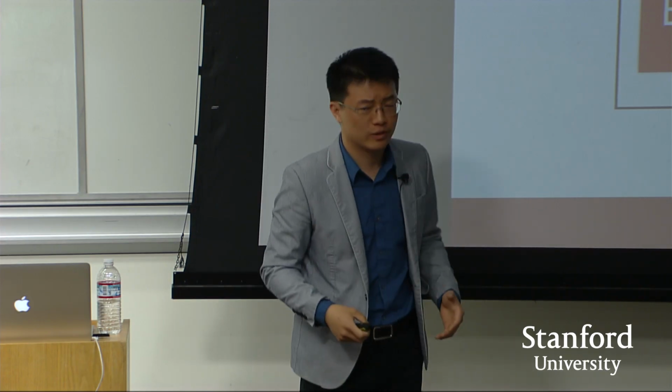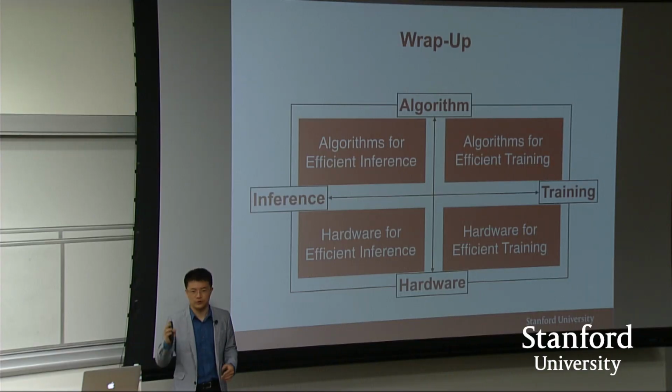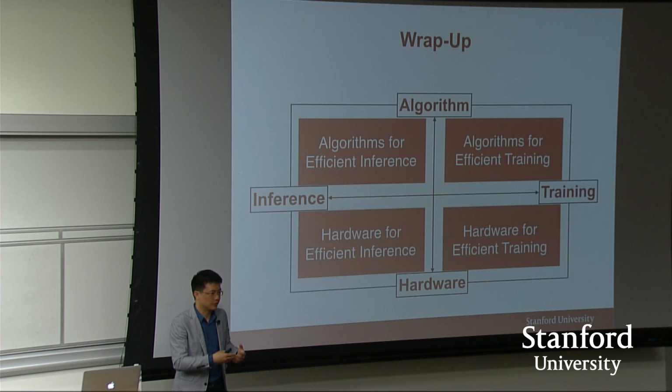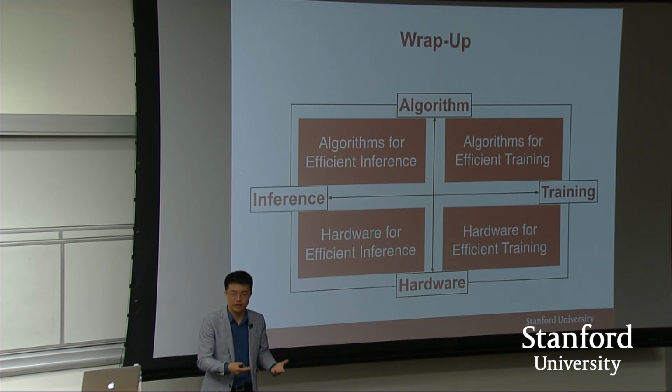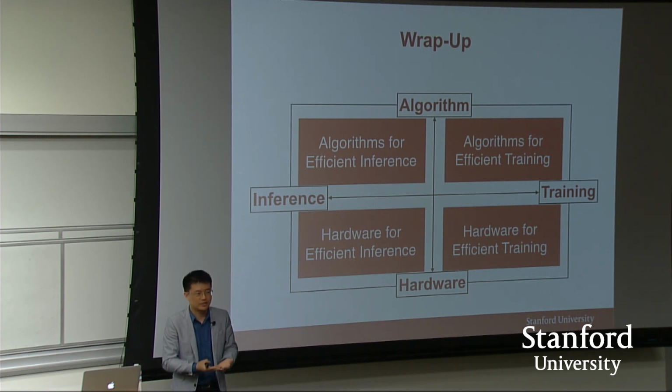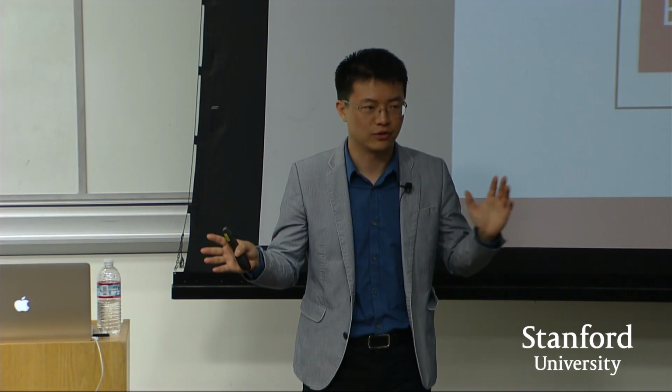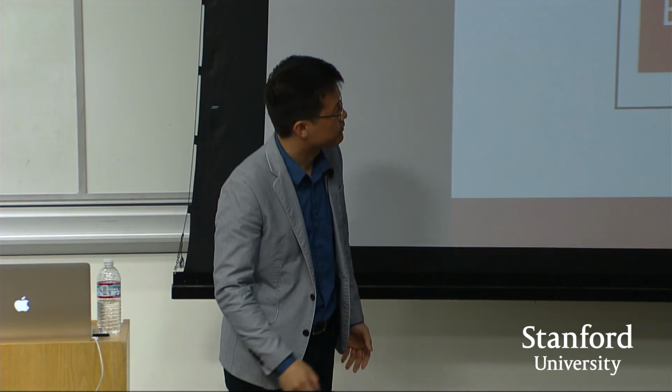And also the efficient algorithms for training, for example, how do we do parallelization, and the most recent research on how we use mixed precision training by taking advantage of FP16 rather than FP32 to do training, which is four times saving in energy and four times saving in area, which doesn't quite sacrifice the accuracy you get from the training.